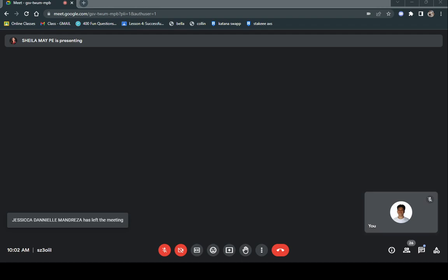Okay. So letter D, we have VD, which is VDD minus IDRD. VDD is 20. ID is 3.32 milli. RD is 2,200. So 20 minus 3.32 times 10 to the negative 3 times 2,200. So this is 12.70.